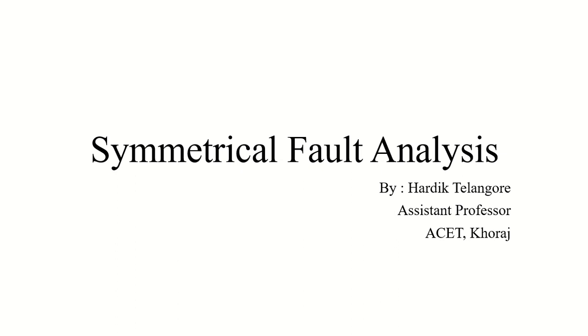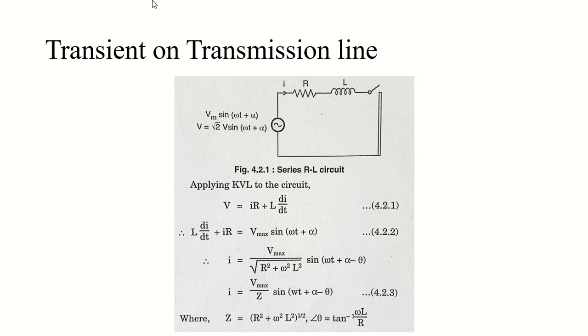So now we've talked about it, let's get moving and talk about symmetrical fault analysis today. First, what is a symmetrical fault? A symmetrical fault is a solid three-phase short circuit, right? Such faults are produced in the system because of insulation failure of equipment, or it can be accidental faulty operation, or it can also happen because of the flashover of lines, because of the lightning stroke.